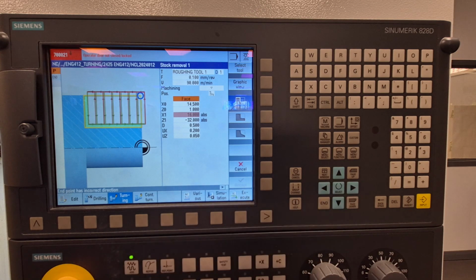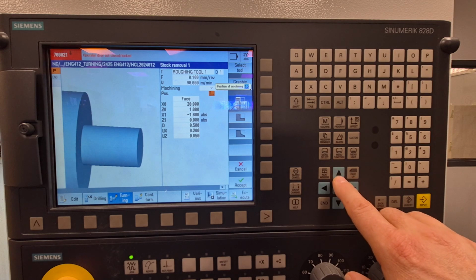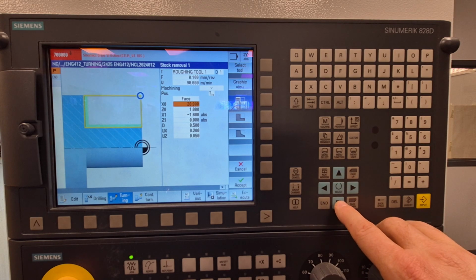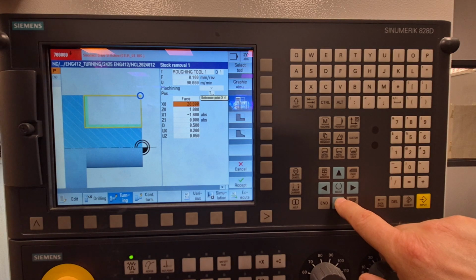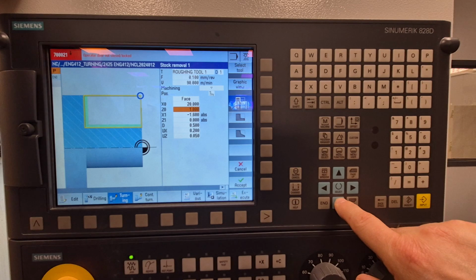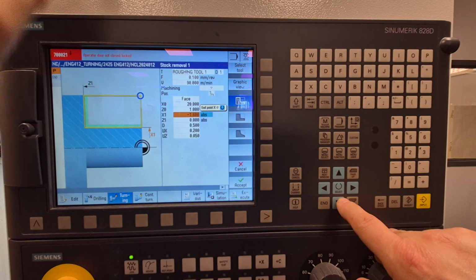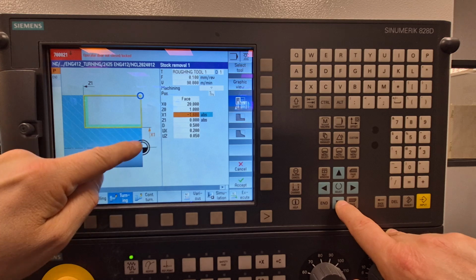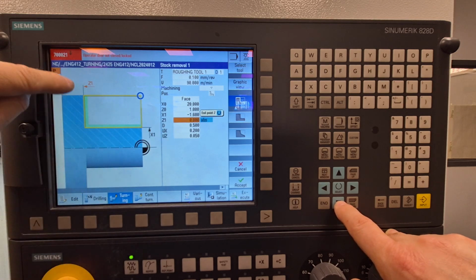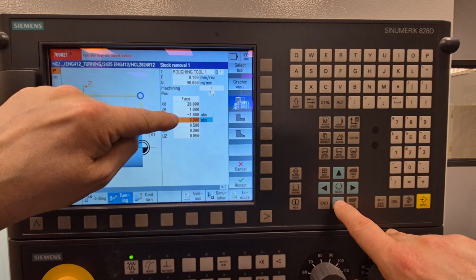Right, so face, that's what I want to do. So when I'm facing off, that's the one I want to use. Face off, 20 mil was the bar, so this particular corner is 20 mil. Now when it's about 19, we don't want to crash into it, so I'm going to call it 20. This one here is how much material is in front of the surface. This here is how much you want to go through. So you see as it feeds through here, I want to go past the center line, so I'm going to put minus 1.6. This one here is, well, where's this face? That's Z0. So 1 mil in front is what was left on it, that's Z0.